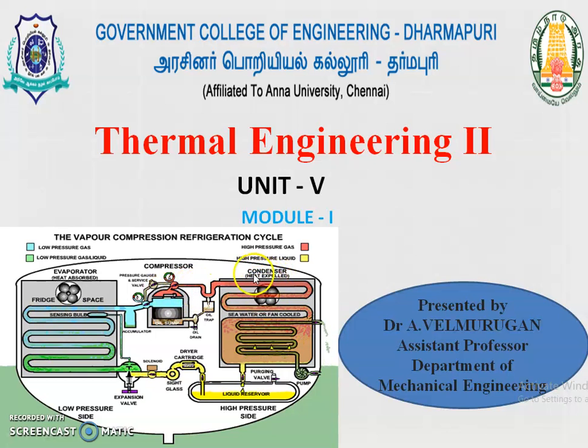The condenser functions as a heat exchanger. With the help of a water pump or an air medium, we cool this hot vapor. Then the vapor goes to the receiver tank, which is a high pressure tank.